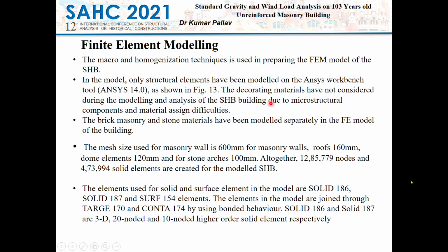We didn't consider any decorative material for this particular work, and also in the current work we haven't considered the cracks, etc. We just prepared a model based on the actual dimensions, and the mesh size were used after convergence criteria. So we have used 600 mm for the masonry wall.